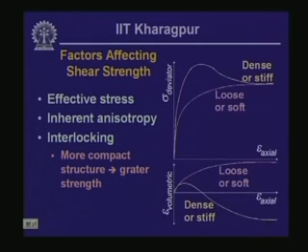And that is illustrated when we consider typical deviatoric stress versus epsilon axial plot and volumetric strain versus epsilon axial plot obtained from triaxial tests for a loose or soft deposit and dense or stiff deposit, as we see on the schematic plot on the right of this particular slide.